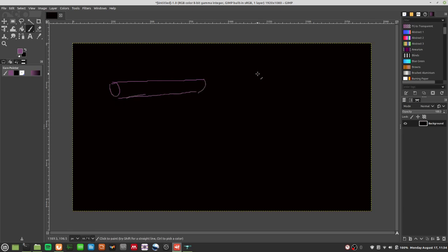At the boundary, what OpenFOAM will do using this boundary condition is treat it as if it's a 1D surface, where you have T fluid here and T ambient here, and then of course you have your layering. So it's not a cylindrical case, but you treat it as if it was 1D, and that's the mathematical formula they will be using.